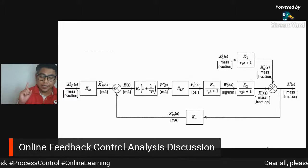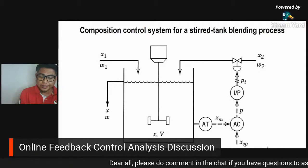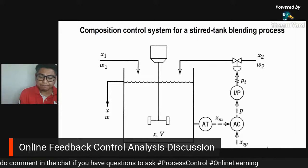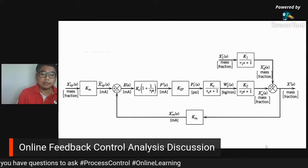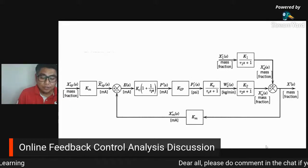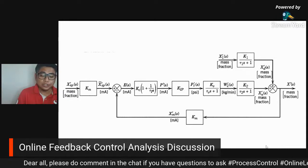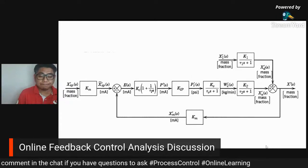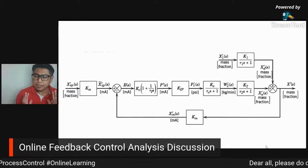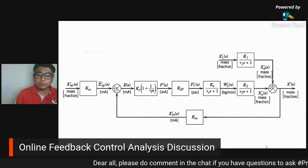One important thing that you need to do is transform from this process diagram into a block diagram with all information related to the transfer functions and also the stream information. Remember, streams need to be labeled in terms of variables and also in terms of units.